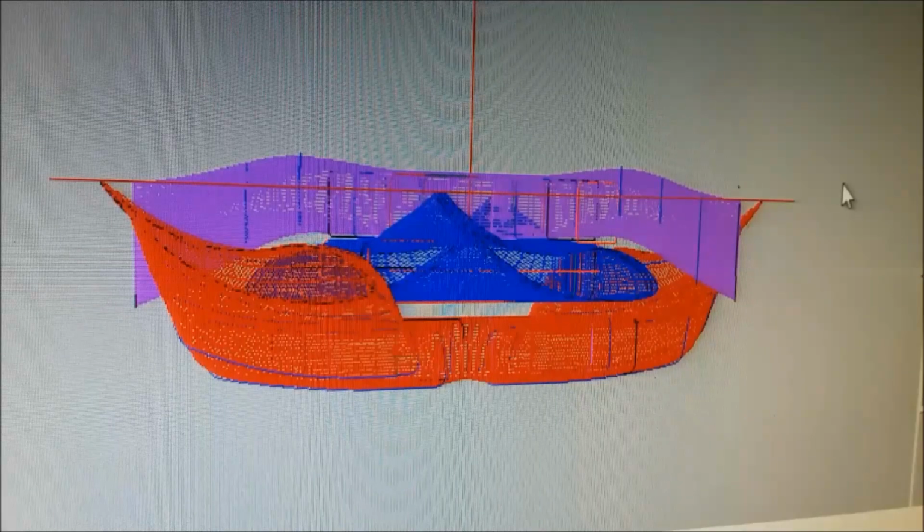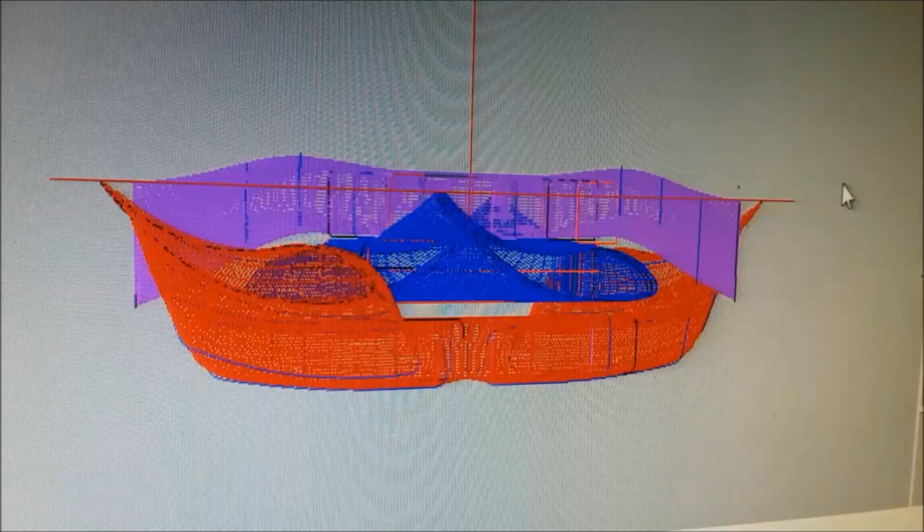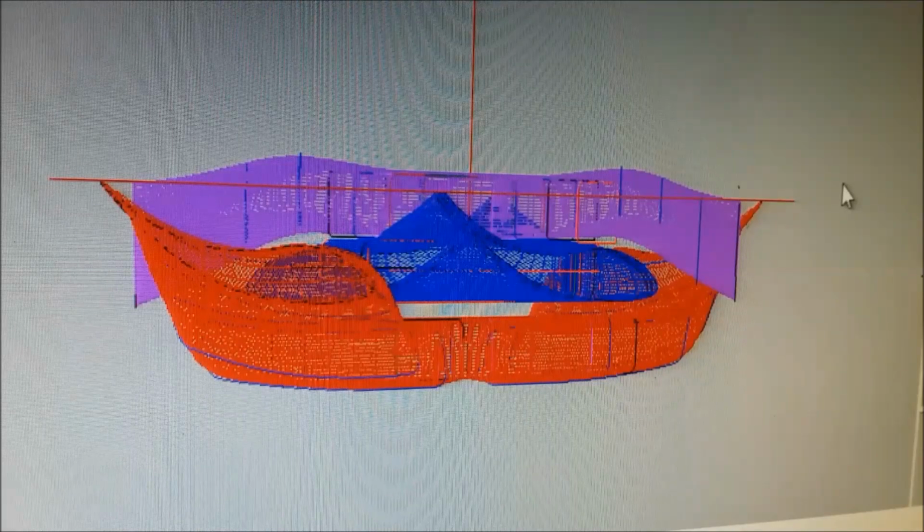And then we put a little pencil X on the ceiling, get on a ladder, and measure from the leading edge to where it cuts the air up to that tape. And we write down what the measurements are. And we're finding 0.7 of a centimeter difference between one blade and the other on a brand new fan.